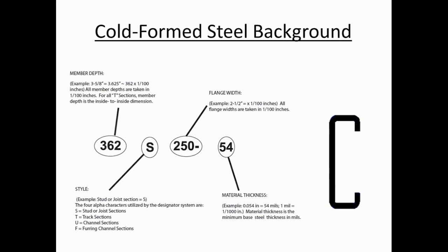Take a piece of paper, 8.5 by 11, and try to stand it up on its edge, and it'll collapse. It cannot keep itself erect. If you take that same piece of paper and fold it in half, you generate stiffness and strength, and that is exactly what's happening in a C-shaped stud.